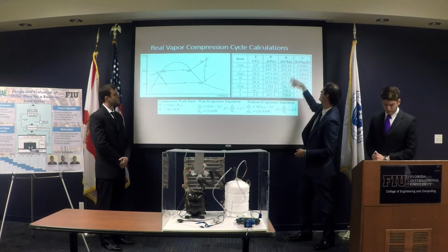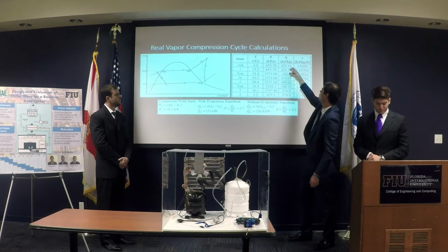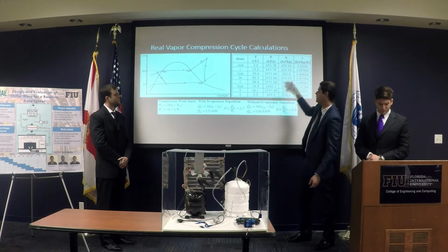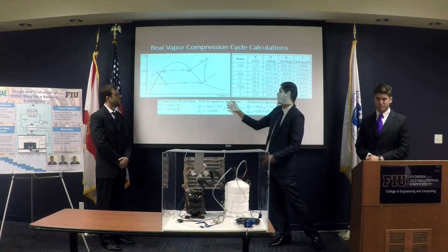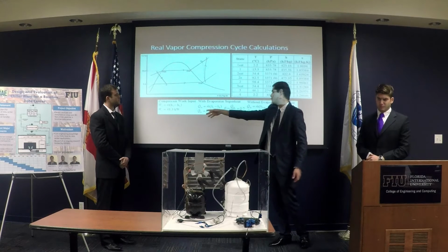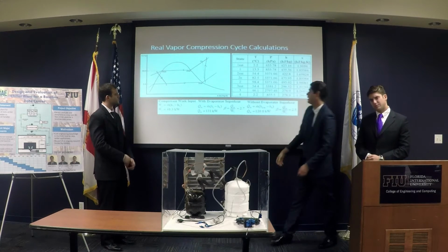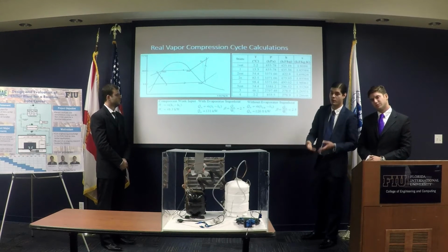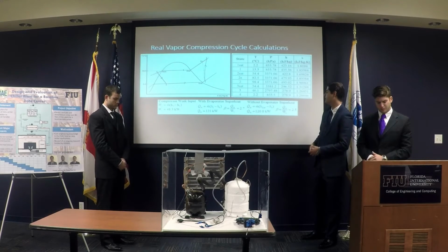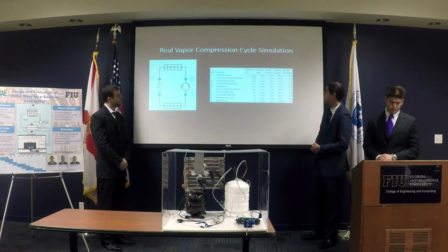But by having mainly the defined properties, we can use these enthalpies and these formulas here to calculate the actual cooling capacity, the work in the compressor, the cooling capacity using superheat or without the superheat, and the coefficient of performance.